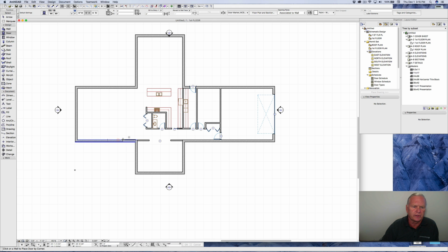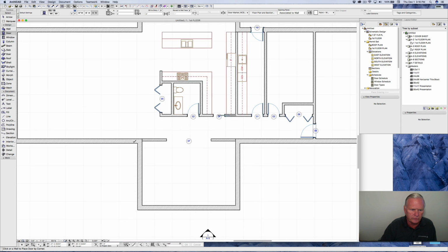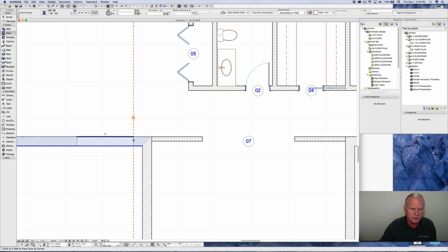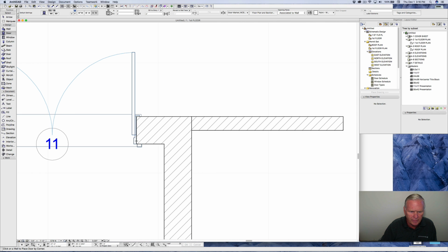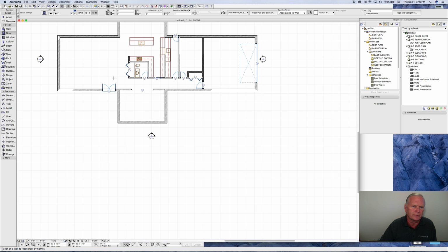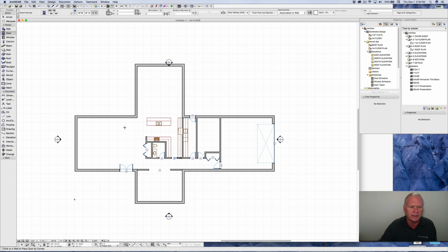We're going to want to insert it here, and probably with the other anchor point, and highlight this wall, get our guideline. Let's go over a foot there, D1, and enter. Zoom in a little bit, and just click on, again, the outside edge of the wall, and move to the inside, and that's the way the doors will swing. And you can see we've got a jamb, a rabbited jamb, and we've got casing, and we've got our threshold lines. And that was because we brought those all over by injecting them in.